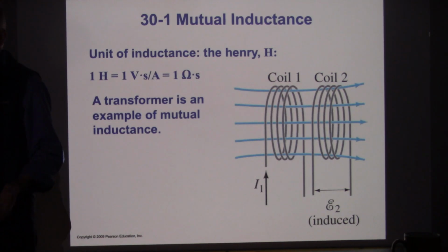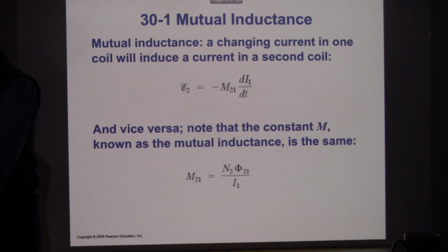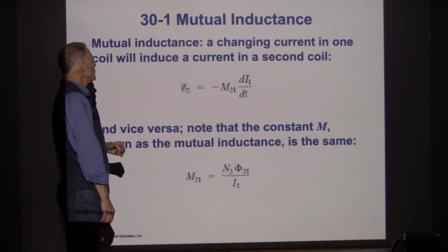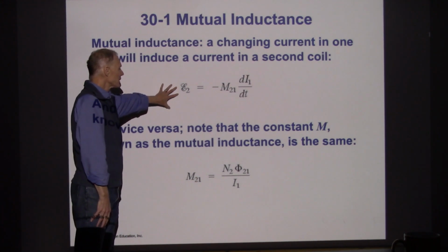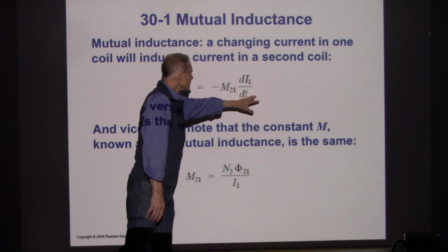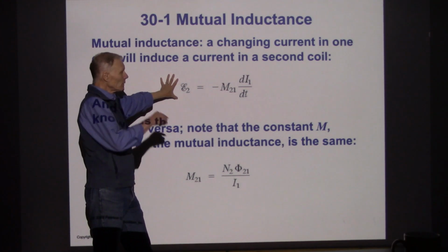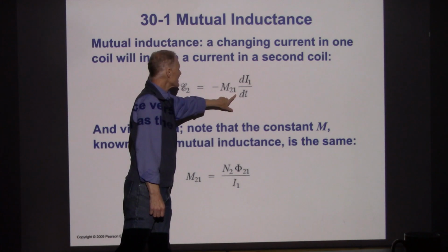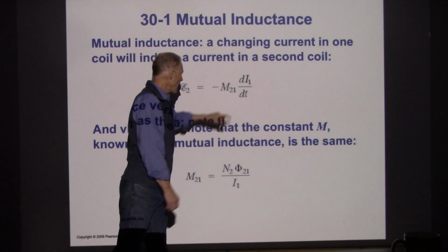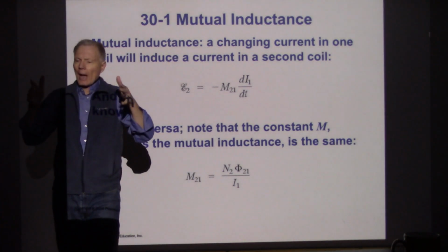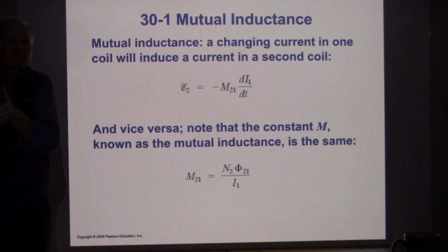Now there's actually a unit for this. They're called henries, and the official formulas look like this. Now we're not going to do that much with mutual inductance. This is mostly conceptual, just to understand what's going on. But what we say is that the EMF set up in one set of wires is a result of the charges accelerating in another set of wires, and that factor, the mutual inductance, depends on how many loops we've got and how close they're placed together.